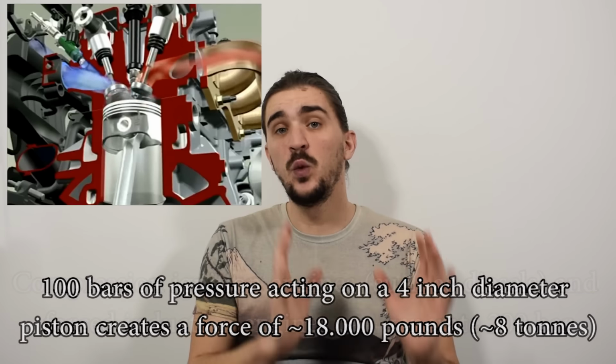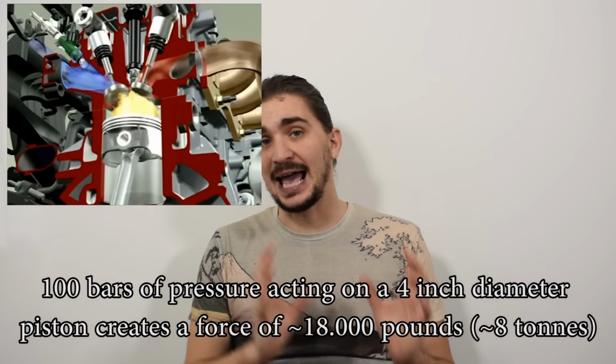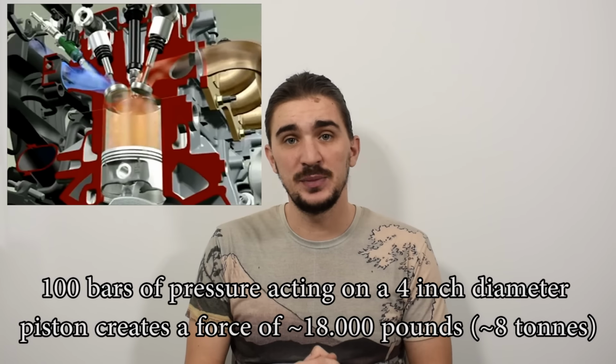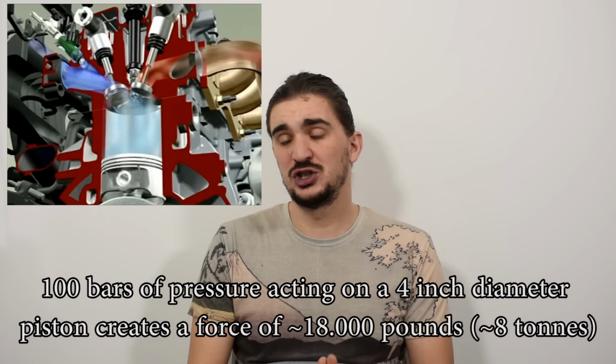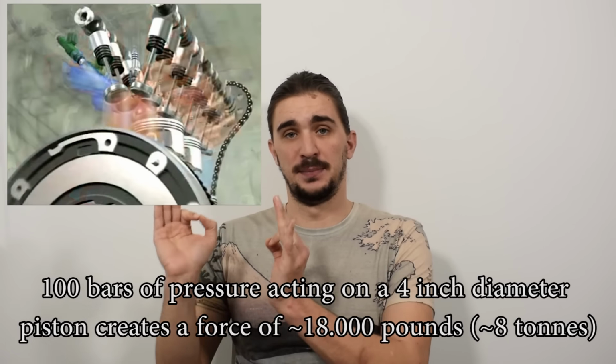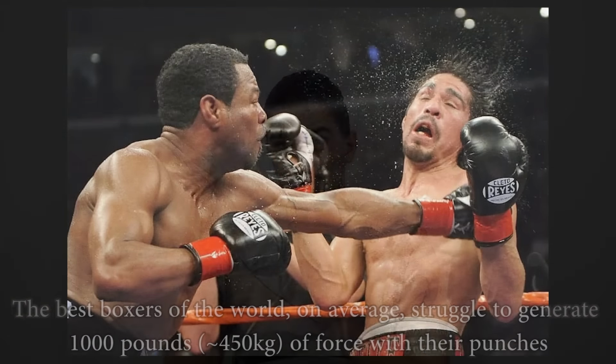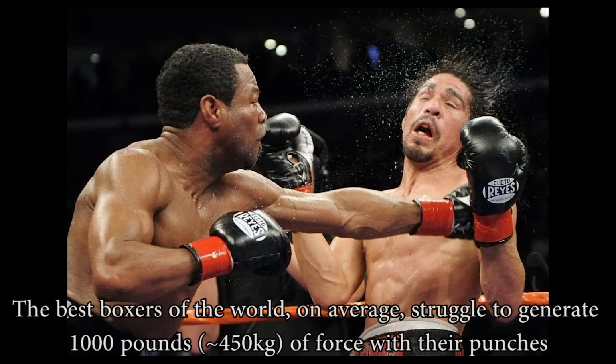pressures. Now, a 100 bar combustion pressure acting on a 4-inch diameter piston, which is around 10 centimeters, is going to generate a force of around 18,000 pounds. That's around 8 tons. To put this into perspective, the best and strongest boxers in the world, their punches usually struggle to generate around 1,000 pounds.